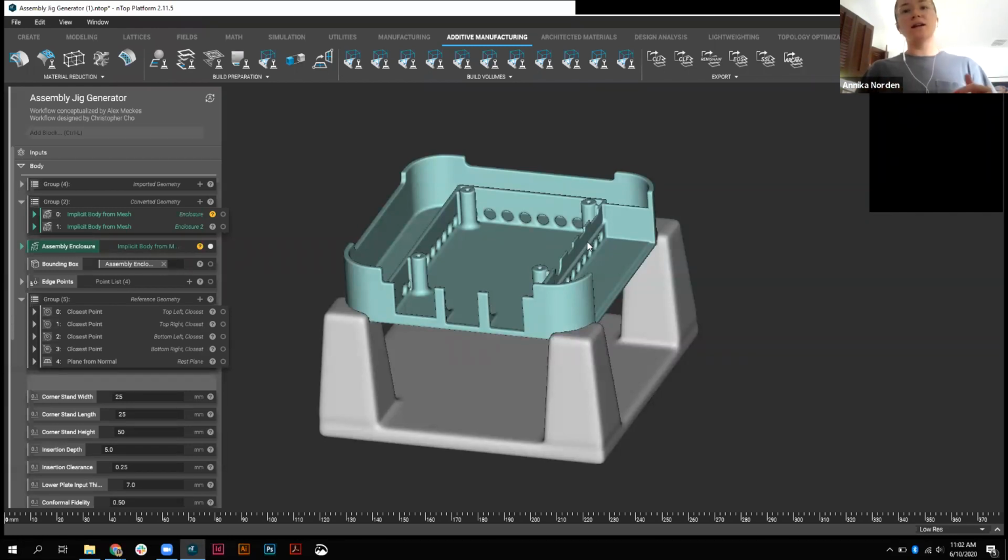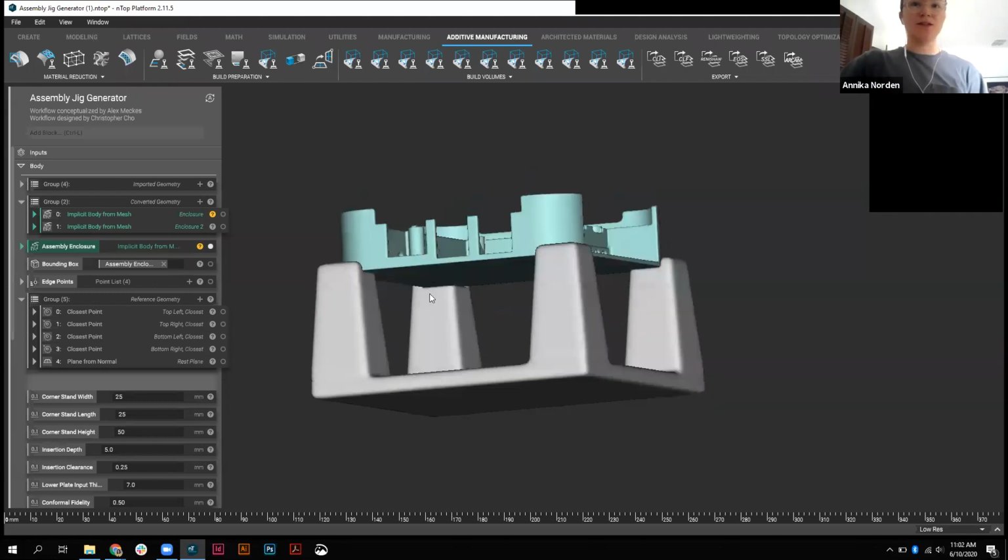One way to help this is by creating a jig that elevates your part off of your lab bench, maybe using a specific material to help keep the static energy dispersed and away from what you're working on. So that's what we're creating here. I guess we can just jump into the workflow.